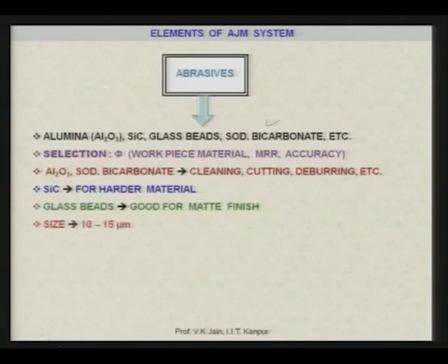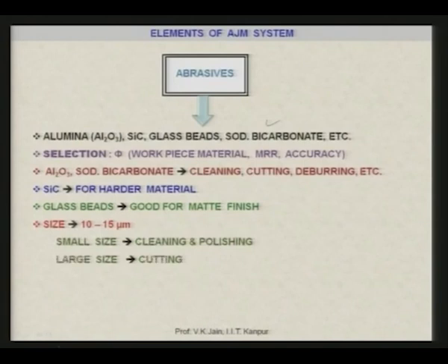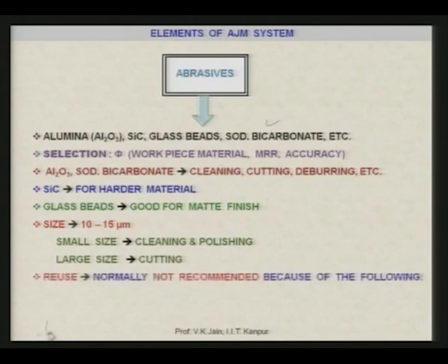The size of the abrasive particles normally used is 10 to 15 micron. The small size abrasive particles are good for cleaning purposes and finishing purposes. Large size abrasive particles are good for cutting, because they can give you a higher material removal rate as compared to the small size abrasive particles.